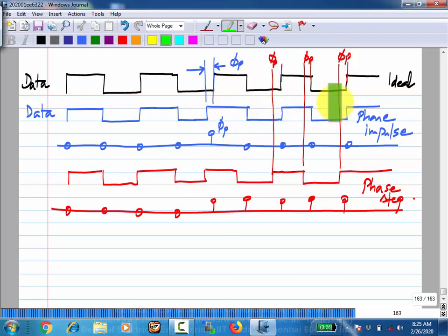Because from sample to sample, the phase is changing polarity. That is like a signal at fs by 2, that is the maximum frequency that is possible. On the other hand, it can be like a whole bunch of edges can be advanced. The amount of advance slowly reduces and the edges become aligned, and then they start going the other way. They start sliding off to the left. So that is like a low frequency phase signal.